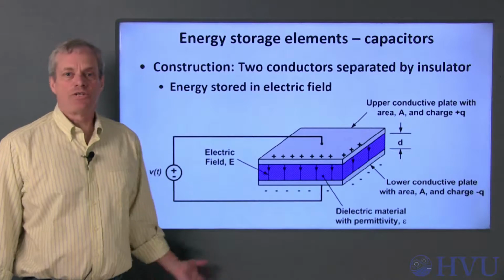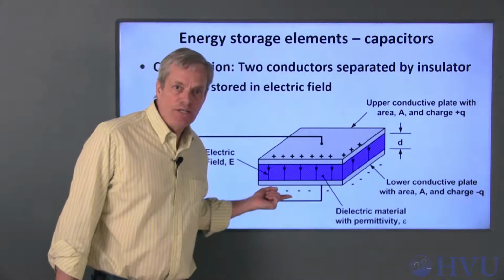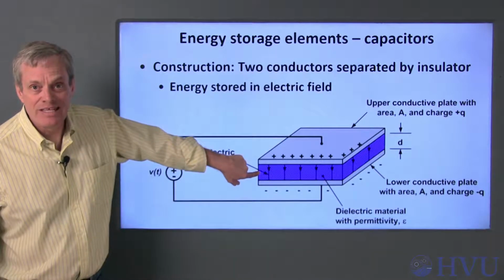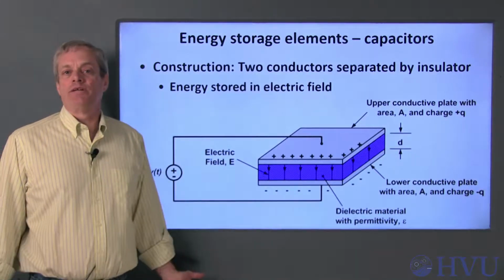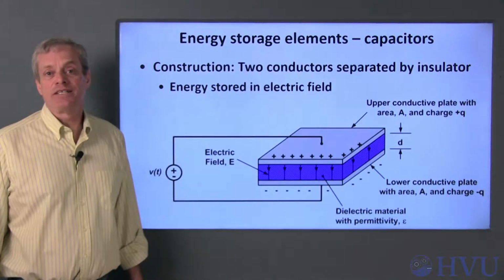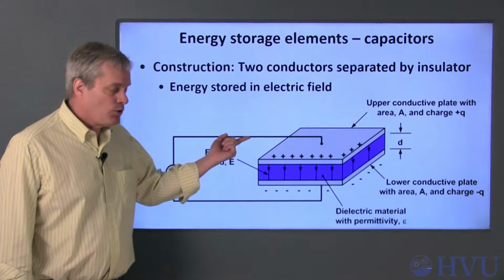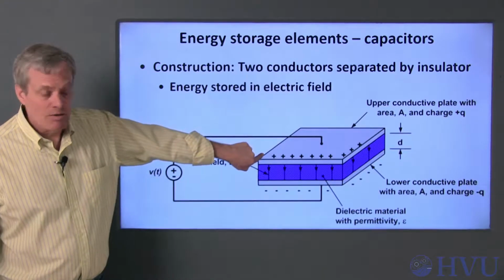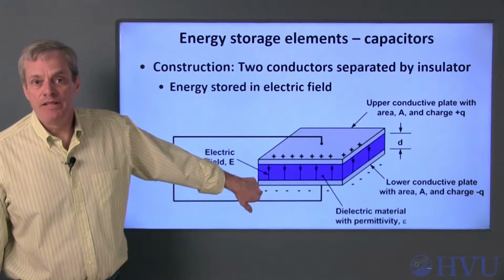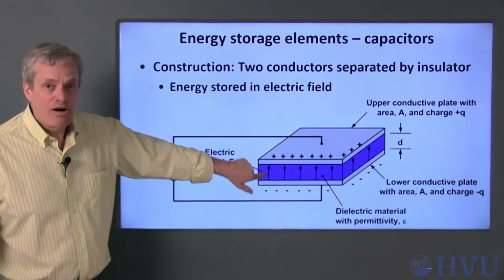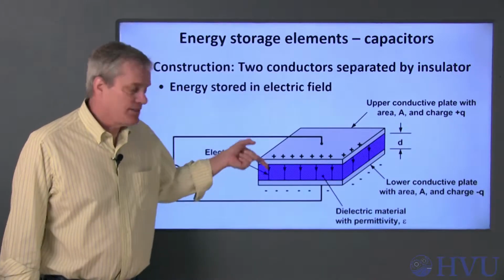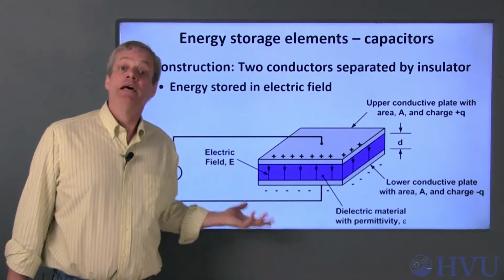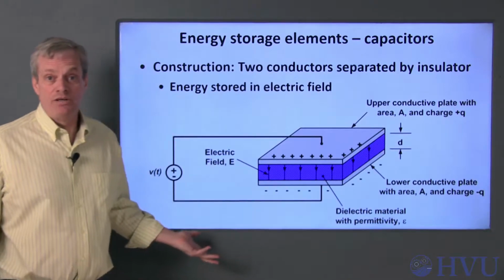Physically, capacitors are constructed by separating two conductive materials with an electrical insulator. Electrical insulators, or dielectrics, don't conduct electricity. So when we apply a voltage difference between the two plates, positive charges build up on one plate and negative charges build up on the other. The separated charges create an electric field in the material between the plates. This electric field stores energy.